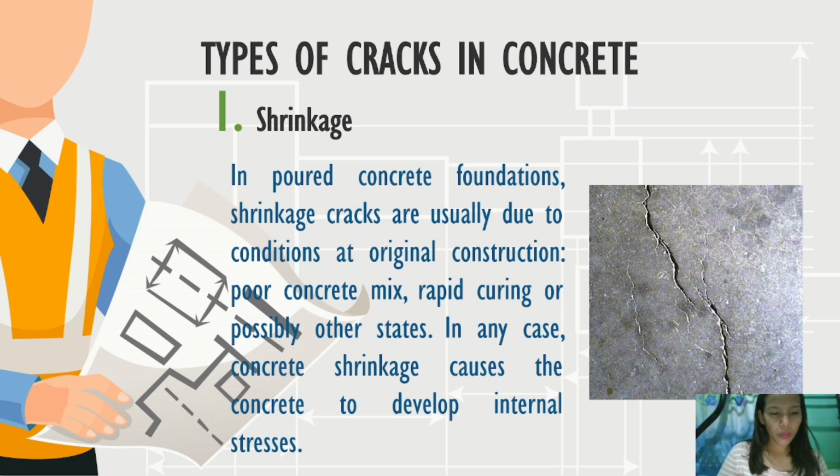In poured concrete foundations, shrinkage cracks are usually due to conditions at original construction, poor concrete mix, rapid curing, or possibly other causes. In any case, concrete shrinkage causes the concrete to develop internal stresses.